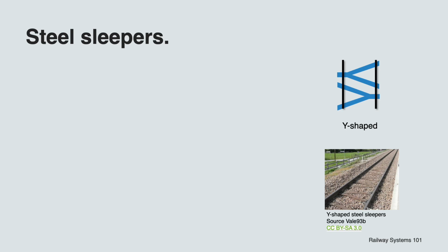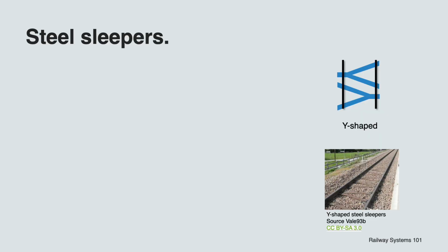As for Y-shaped sleepers, disadvantages of the through sleepers are mitigated due to the continuous shape, which makes them highly resistant to displacement while reducing their footprint. For this reason, Y-shaped steel sleepers are being used in challenging situations such as steep climbs and very tight bends, while delivering a high stability and a high resistance to displacement.